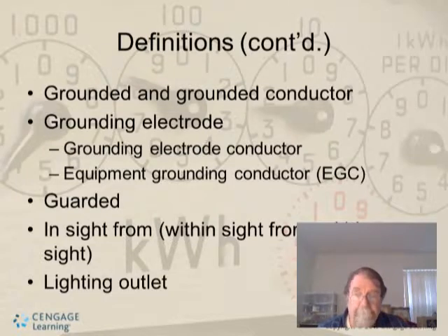Now, guarded is defined as covered, shielded, fenced, enclosed, or otherwise protected by means of suitable covers, casings, barriers, walls, screens, mats, or platforms, effectively removing the likelihood of approach or contact by persons or objects. Panels having doors or covers are considered guarded.